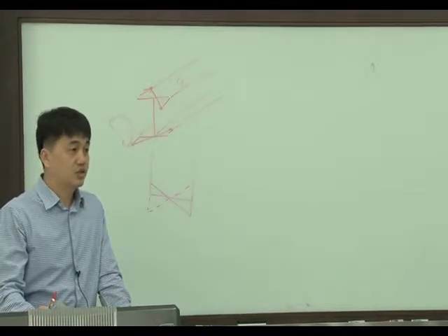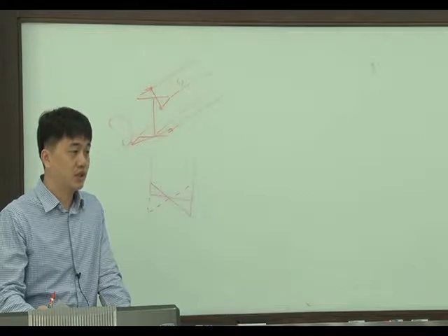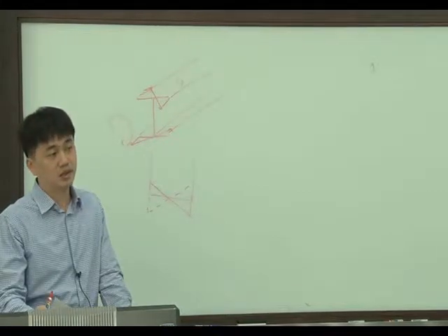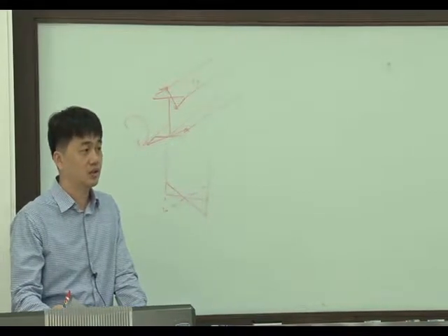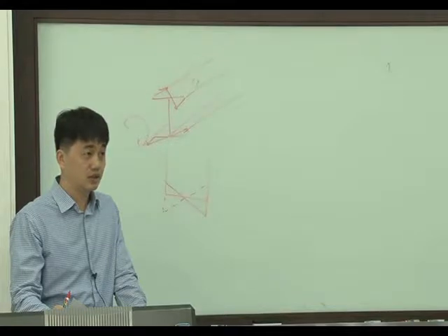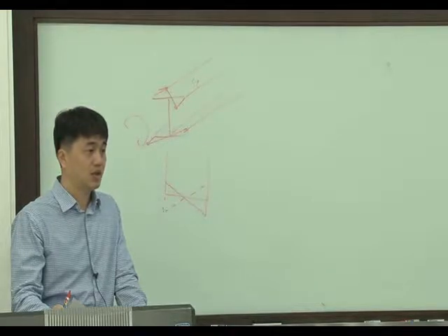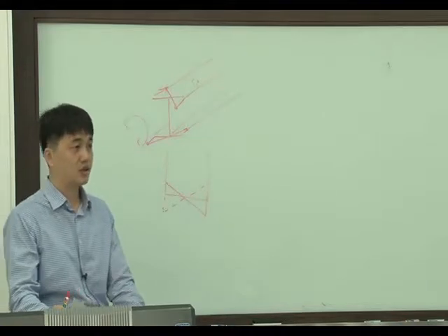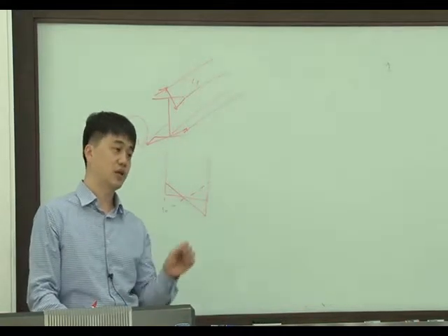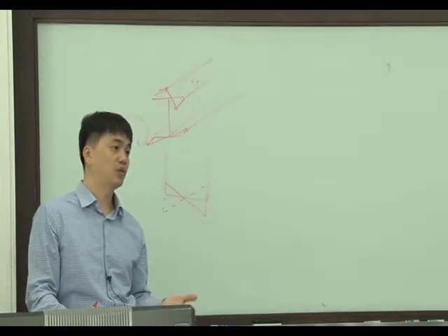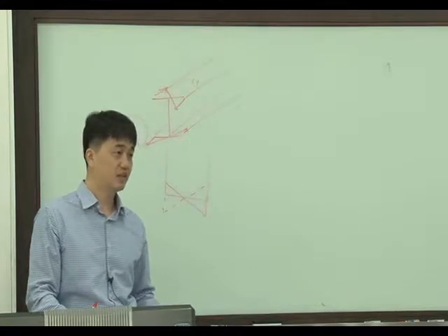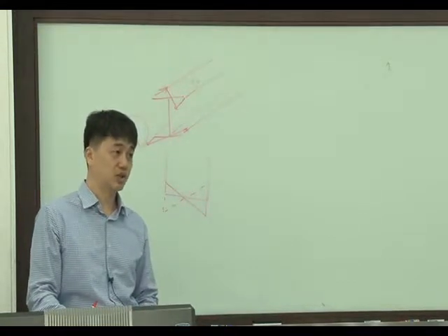So in general, in Euler beam theory and Timoshenko beam theory, this warping is not considered, right? So Timoshenko and Euler beam theory cannot properly approximate the twisting behavior. Both theories are only for bending. It's not about twisting.